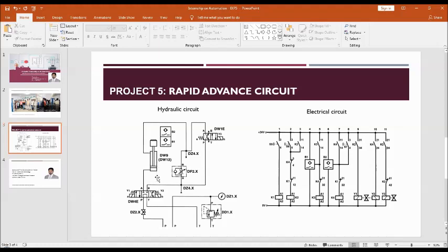But why are we using the second direction control valve? That is for changing the speed from high speed to low speed, or high velocity to low velocity. And we want two different speeds in only one direction. Remember, that is why we are using a throttle check valve. Only one throttle check valve is enough, because we are controlling only the upward movement, not the downward movement. We are also using a pressure relief valve and a pressure gauge. So let me build this circuit.